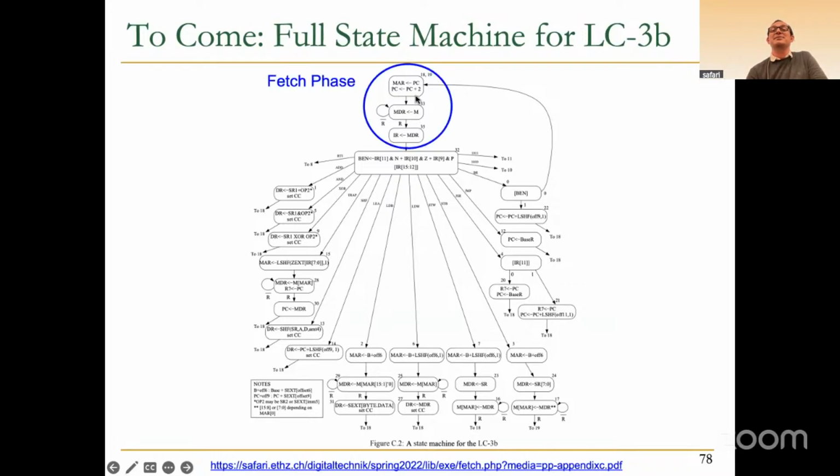If your finite state machine is here, what you do is you generate the control signal such that PC gets loaded into memory address registers, and concurrently, I forgot to say this in the picture, sorry, concurrently you increment the PC by 2, because you're going to go to the next instruction later at some point, right? You could do this later also somewhere, but they decided to do it in this state. And then unconditionally, you jump to next state. Remember, in finite state machines, we have the next state logic. After 1 clock cycle, unconditionally, you go to the next state, okay?